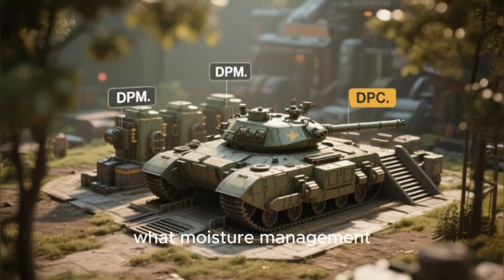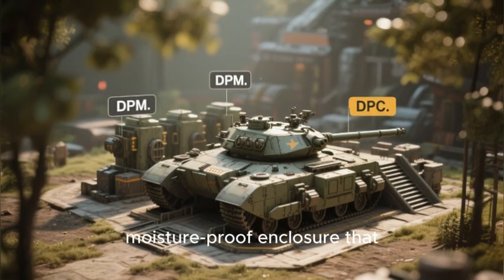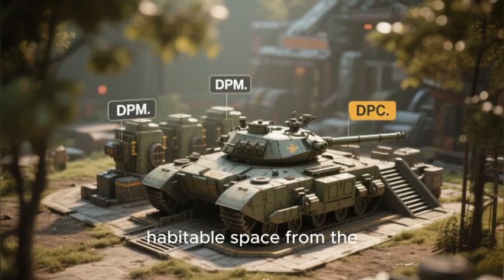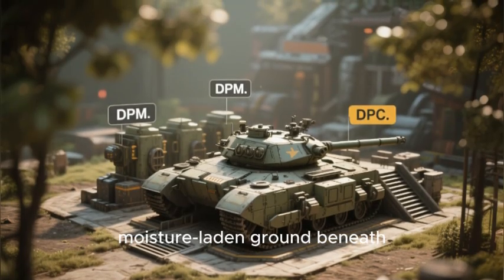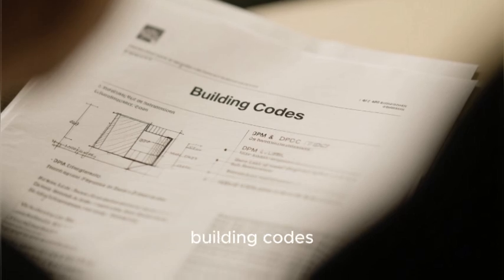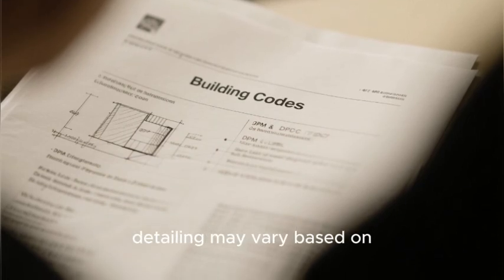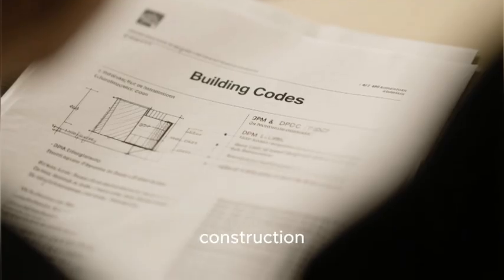This creates what moisture management specialists call a tanked or tray system, a complete moisture-proof enclosure that separates the entire habitable space from the moisture-laden ground. This connection is so vital that building codes explicitly require it, though the specific detailing may vary based on foundation type and wall construction.